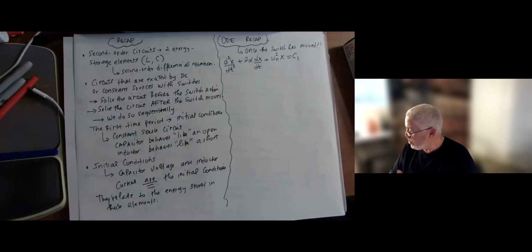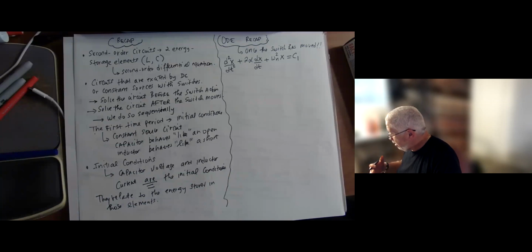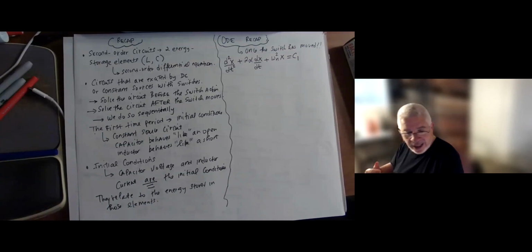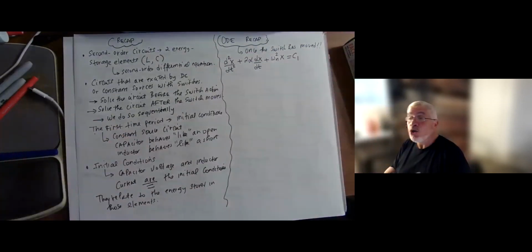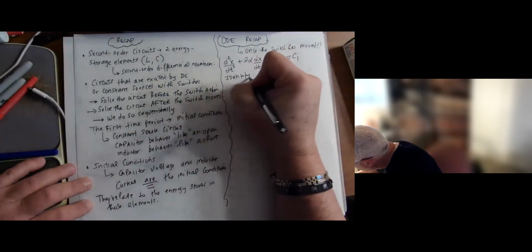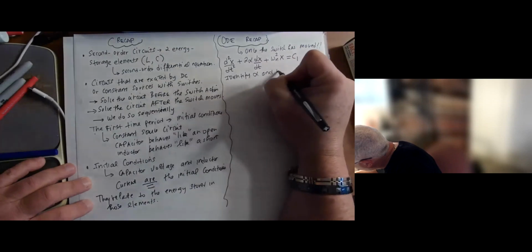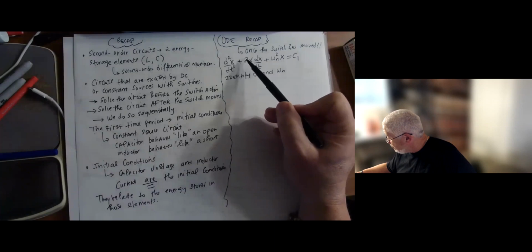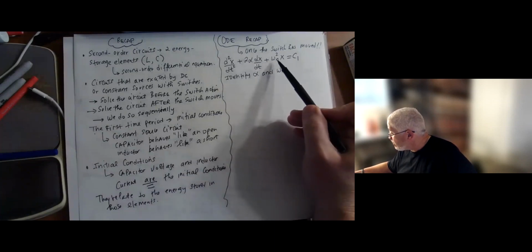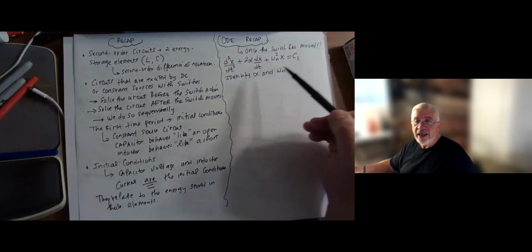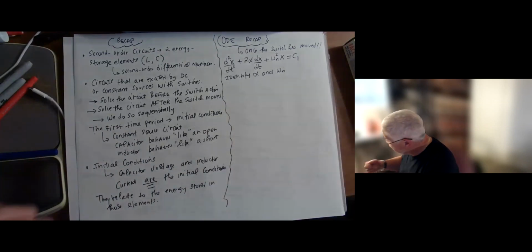So I wanted to broaden that discussion a little bit, bringing in your differential equation content before we do the example here. Once you get this, no proof is required on my part. I don't need you to prove that. What I want you to do is identify alpha and omega n. Alpha is the constant associated with the first-order term divided by 2, and omega n is the square root of the constant associated with x. Then you proceed to tell me which case we're dealing with here.